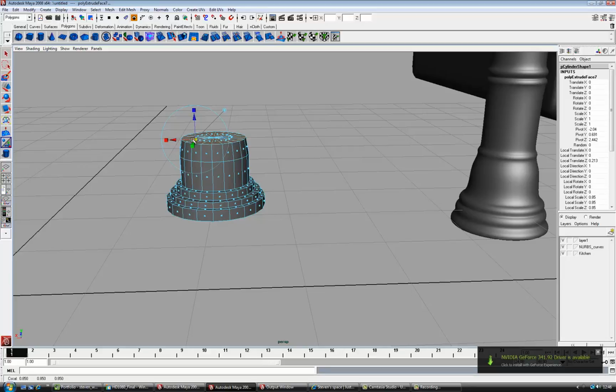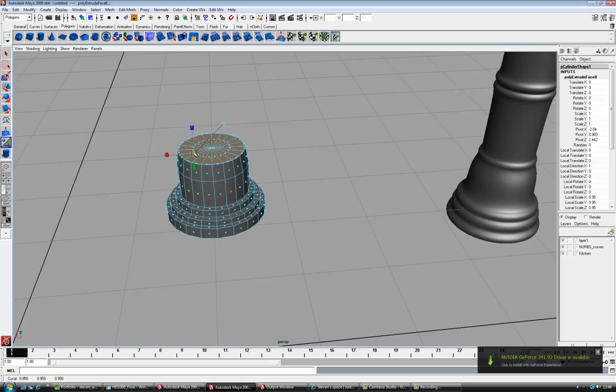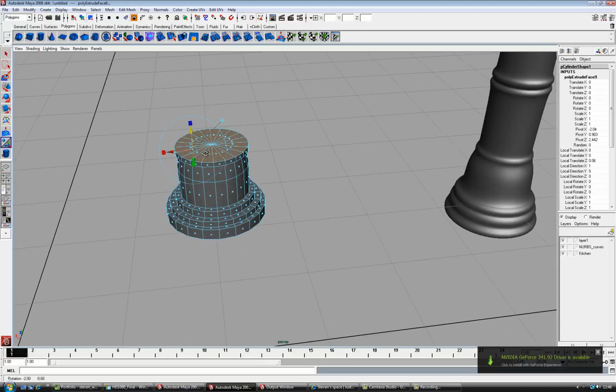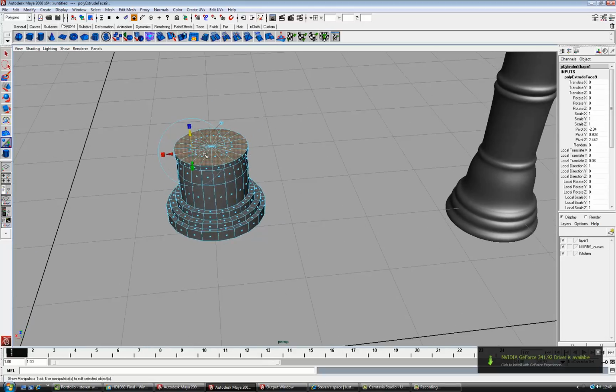And then we want to put another lip in, so the way this is done is G to extrude again. This time I'm gonna scale in a little bit. No, actually I want to scale out, don't I? Scale out. G to repeat the command, which is extrude up. So I've got that little lip sticking out now, but I want the object to move inwards again. So G, scale that in. G again, scale up. So we've got that.